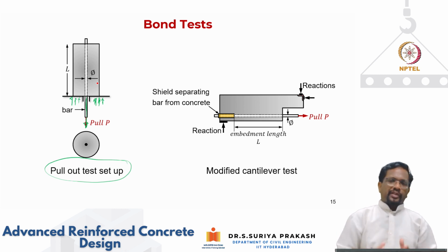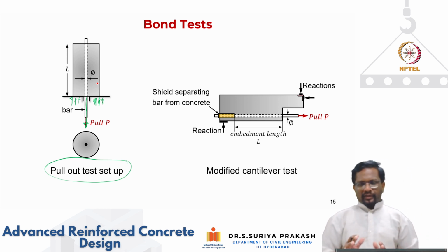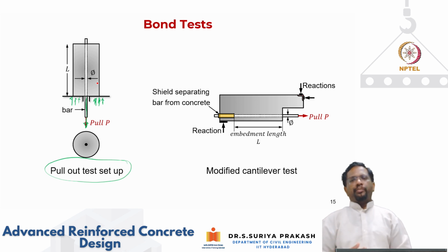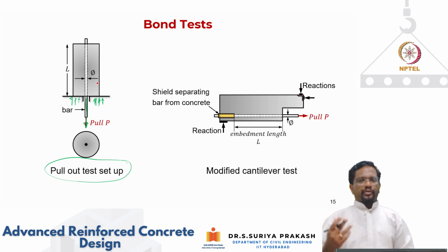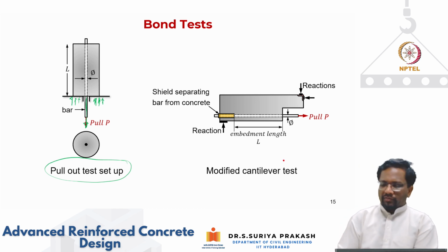So there's going to be an additional confinement for the surrounding concrete because you're holding it for reaction. So whatever result we get may not actually replicate the real scenario that happens in a flexural beam. For that, another test was done, which is called the modified cantilever test.